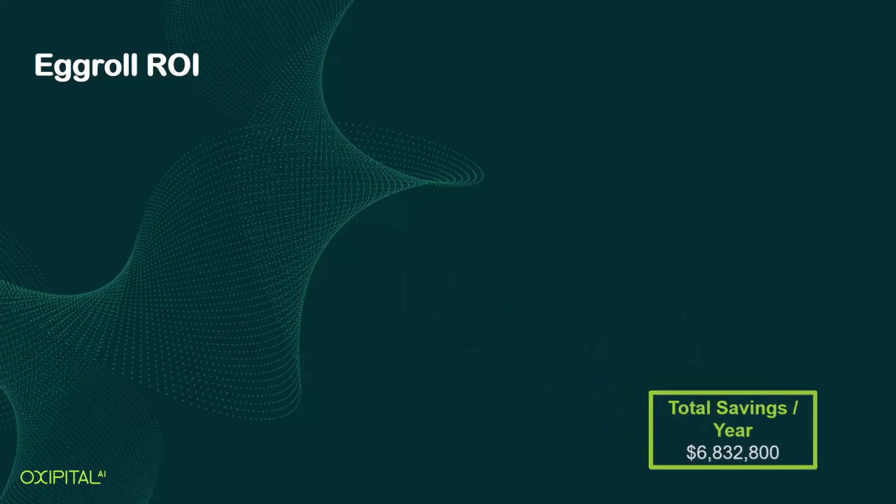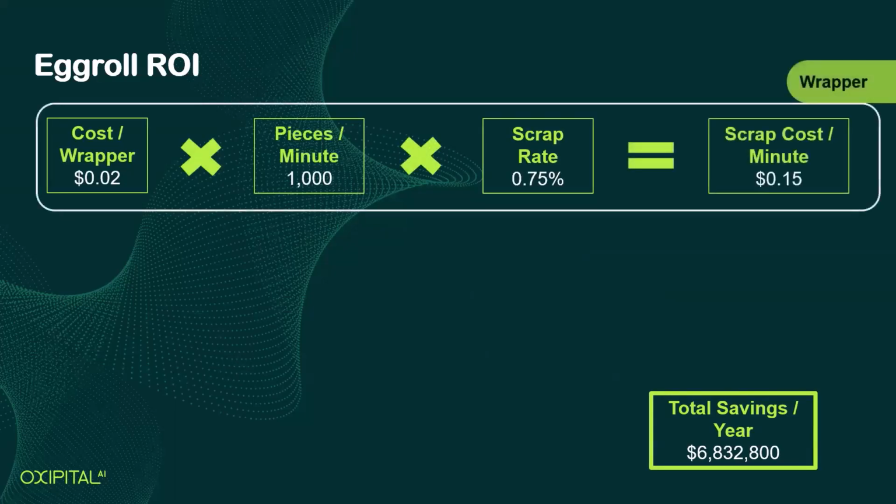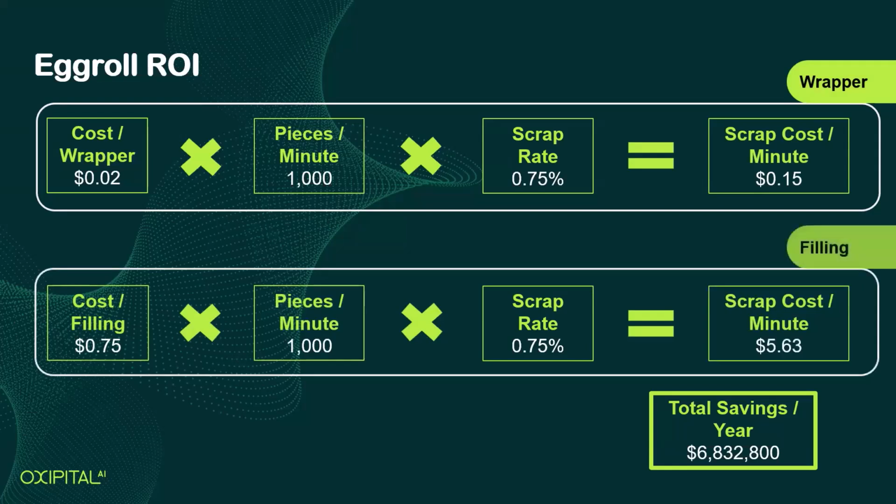Generally, if you can prevent a defect as far upstream as possible, then it will have the lowest impact further down the line and economically. When we identify that the wrapper placement in a fixture prior to the filling can lead to a number of defects that cause downgrade or scrap product, it's a good place to apply a vision inspection solution. An AI-enabled vision solution can look for placement relative to that fixture while also looking for damage to the wrappers.